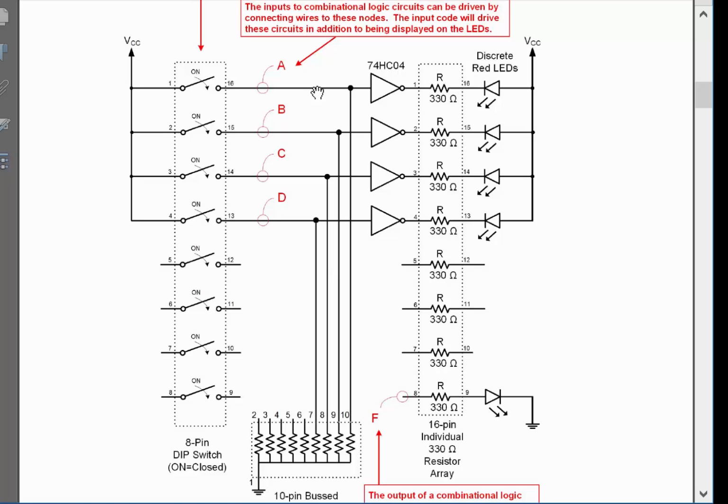So in order to get around this whole problem of shorting the supply to ground when you have the switch closed, what you do is you put a resistor in series with the path. We're going to put a 10K ohm resistor right here, and let's think about the operation. When the switch is not closed, A is pulled to ground through a 10K ohm resistor, and that's fine, it pulls it down to 0. So that works.